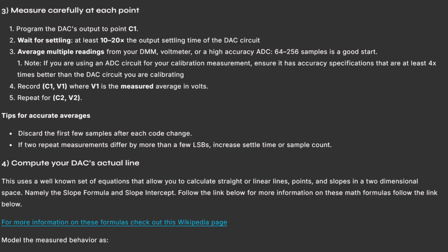So next we want to record our 2 readings. How do we do that? We have to come up with the DAC code that's 10%, enter it in the DAC, we get our output, and we measure that voltage, right? That's our first voltage, then we repeat that for our 90% spot and record that voltage.